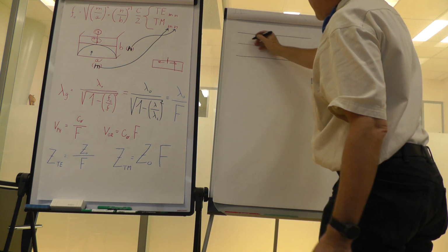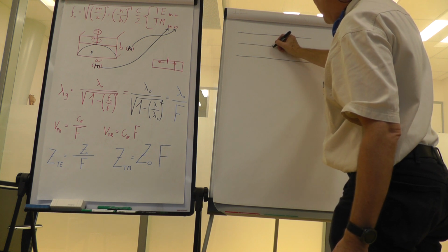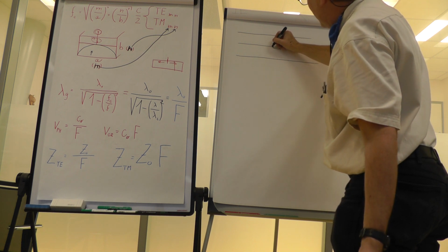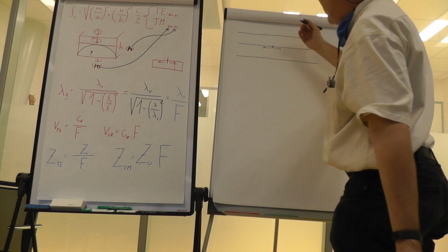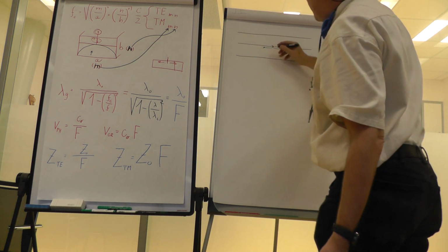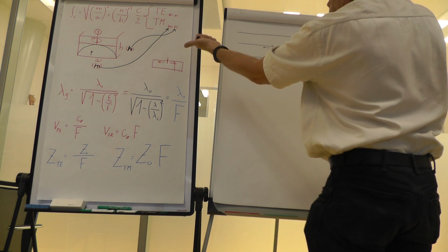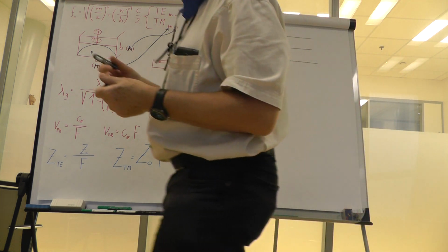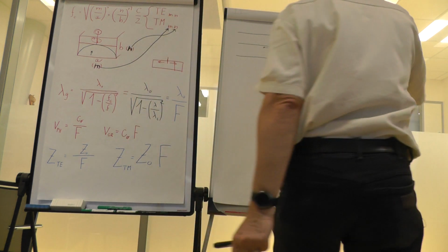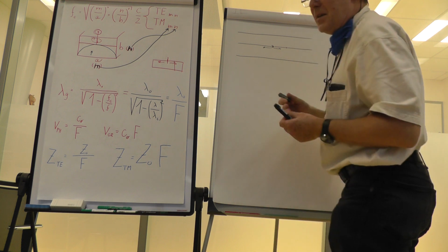So if we have a propagating wave here, a small portion of the energy just comes to the other waveguide through the hole and propagates. But due to Huygens principle, this energy would propagate in both directions, regardless of whether you send the wave there or in that direction. You would have a small source radiating in two directions. Not a very useful device. Well, but what if I drill two holes that are just 1/4 of a wavelength from each other?